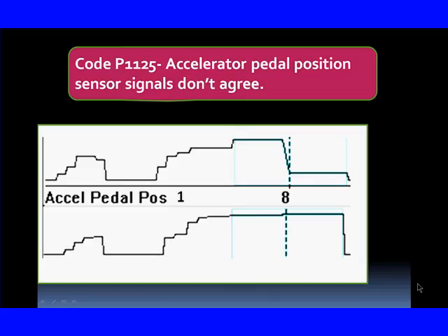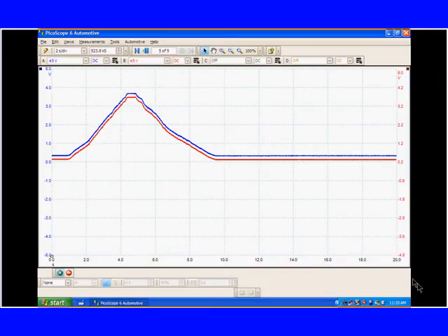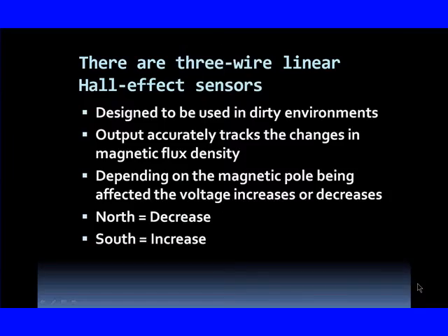So this is an example of what you're going to find with a scan tool. When they don't agree, they agree all along here. Every time we do something, there's pretty much agreement. Here, we can see it real time, high speed, and we can avoid having to worry about missing a dropout. So this is why we use this. Again, we're back at our 2 milliseconds per division, 5 volts. I think we beat up on why that's doing it.